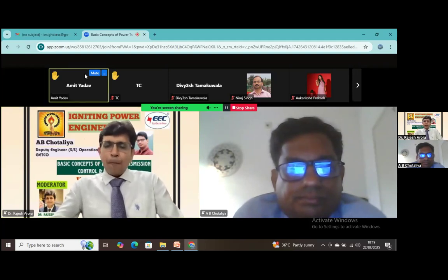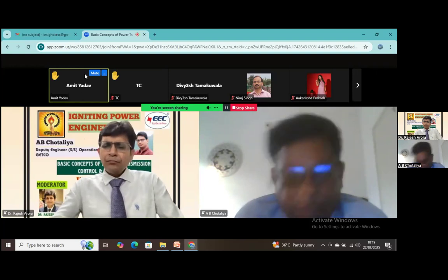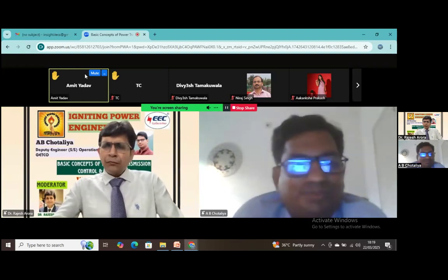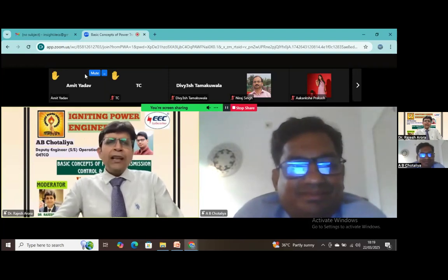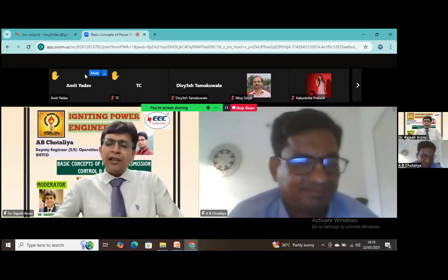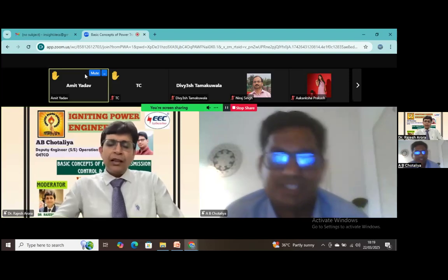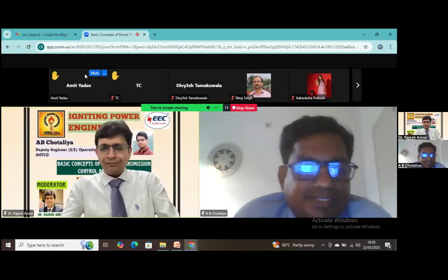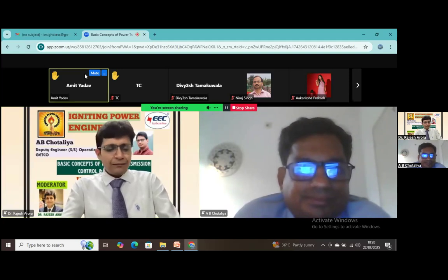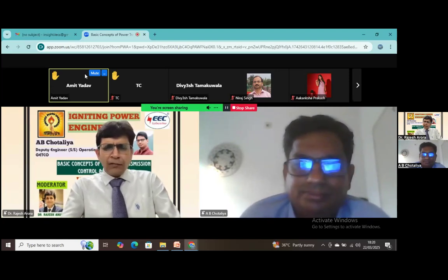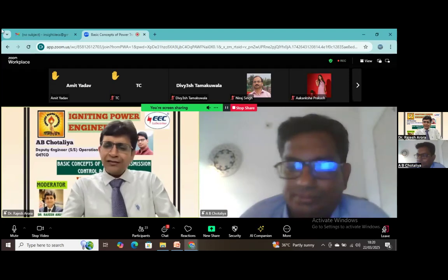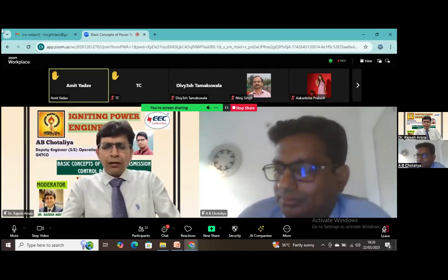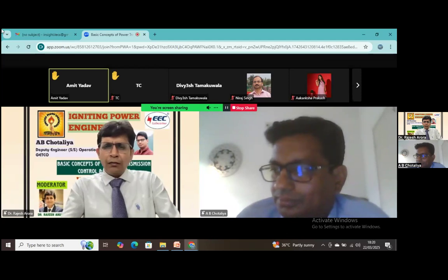The purposes of CVT and PT are different in the substations, no? No, the only additional purpose of a CVT is that it can also be used for the communication system. But can we use a CVT as a PT also? Definitely, no doubt about it, 100%. All the cores are present in the CVTs, you can use all three cores. So why are we using PT and CVT both in 220 kV plus substations, 66 kV plus substations?